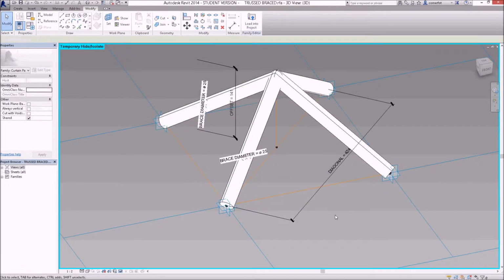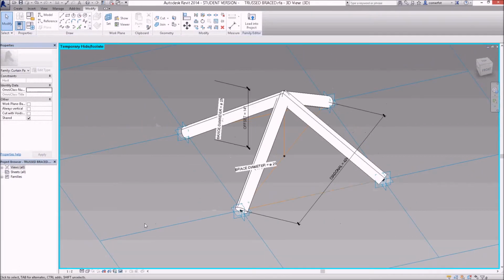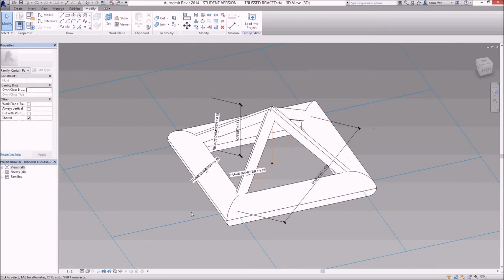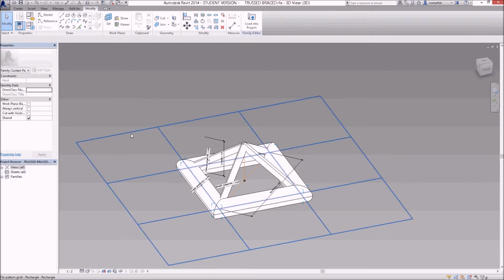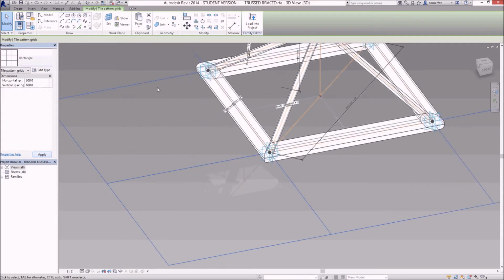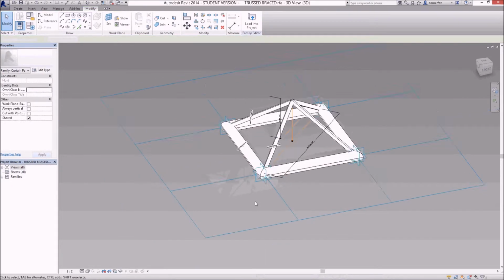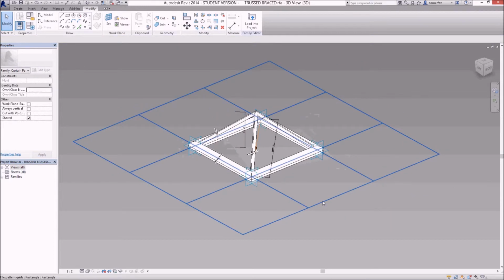Okay. So that's a form, and then I'll go back to my sunglasses down the bottom here and click reset. So I've reset all my geometry. It's looking very big and chunky here at the moment, but that's only because I've changed my rectangle spacing. It's quite small, so I'll go up to 600 again here now. You can see that this is all flexing nicely, and even try a different dimension again just to make sure. Go up to 900.